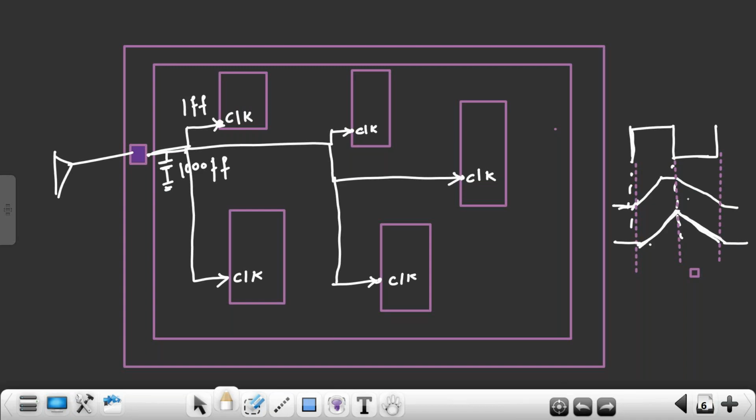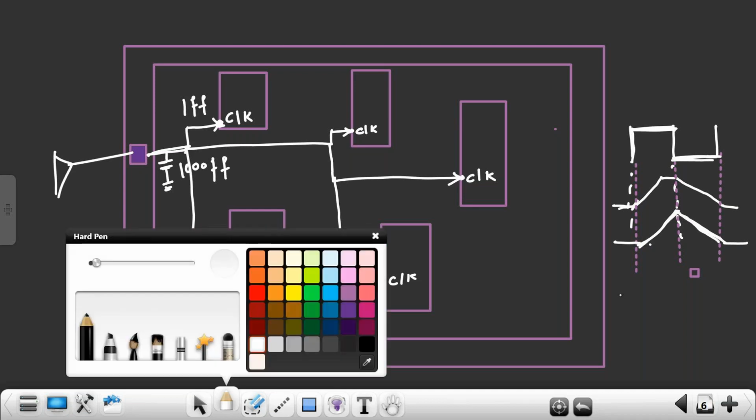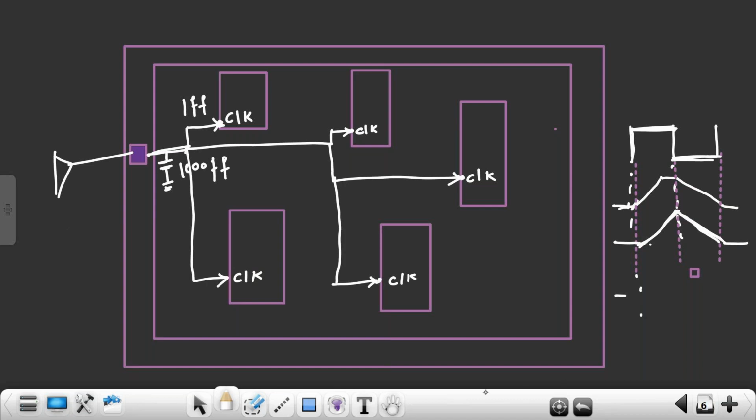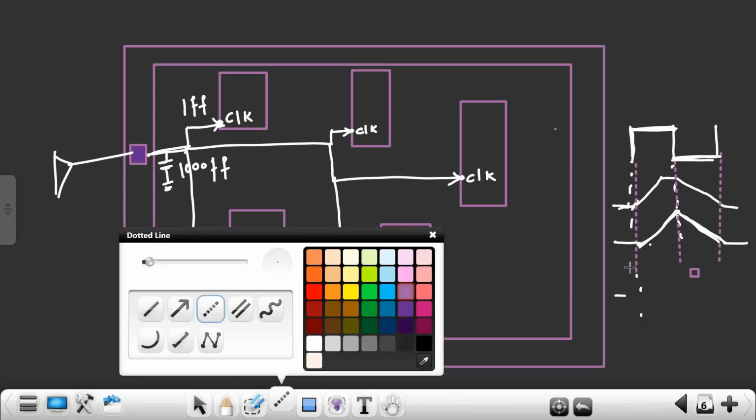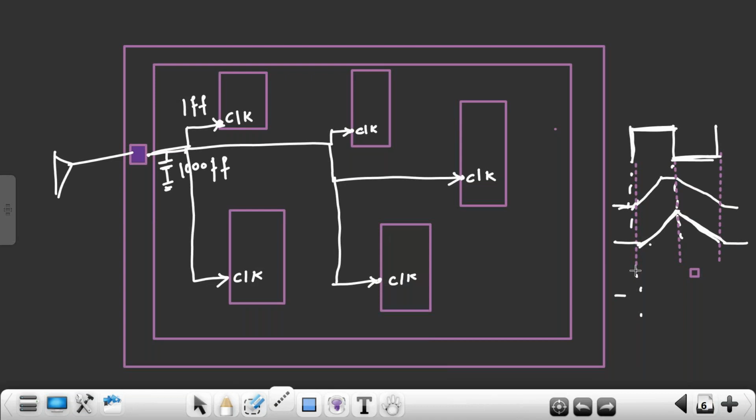So in this clock signal, I don't have the pulse only. This is called the on pulse, and this is called the off pulse. If the pulse is not there, flip-flops may not work properly. So to meet this clock transition, I should have only a small amount of rise transition and a small amount of fall transition.